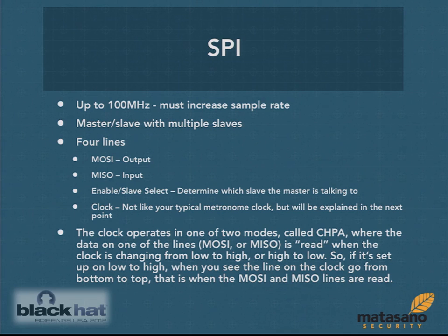The actual hardware has limitations on how fast it can sample things, but you can configure the software to sample things quicker with fewer pins being connected to it. Since I only had 3 pins, I was able to sample at 50 megahertz. So I had to accept a risk that the data I was getting might not be anything because I wasn't able to sample fast enough.